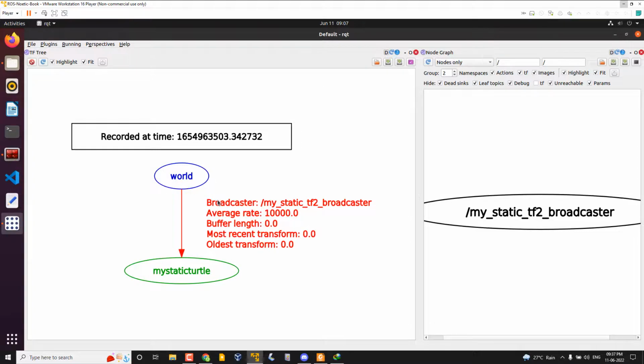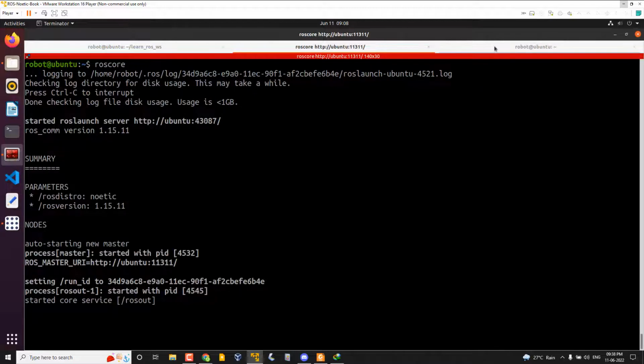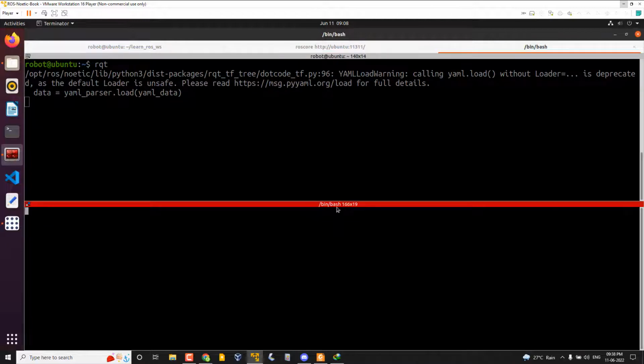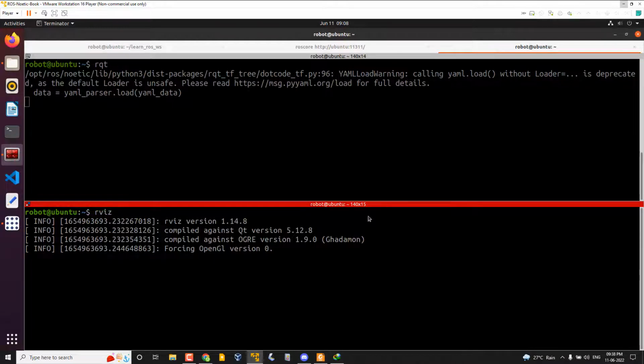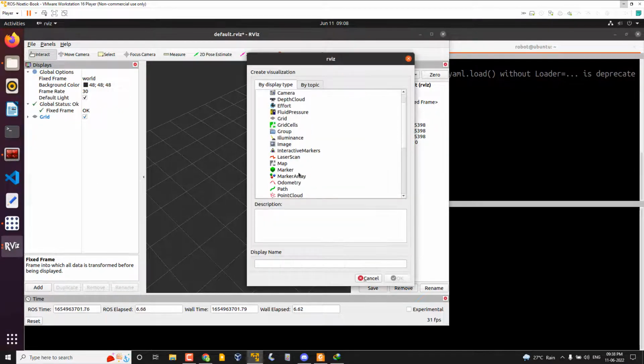The TF is important stuff. So what happened was, this TF is a kind of static TF. It doesn't change, I think. Maybe we can visualize the TF in RViz as well, so we will get clarity about what is happening in the TF. Let me visualize in RViz. The parent frame is world, and then I'm just simply visualizing the TF.